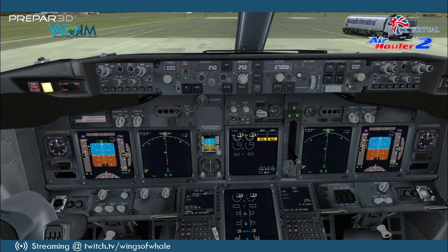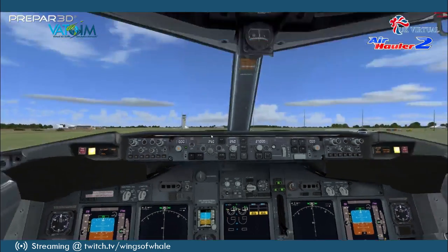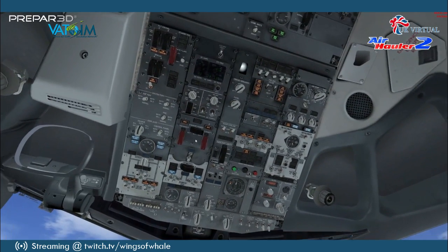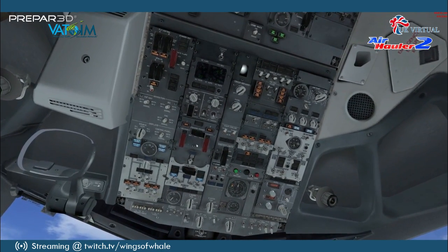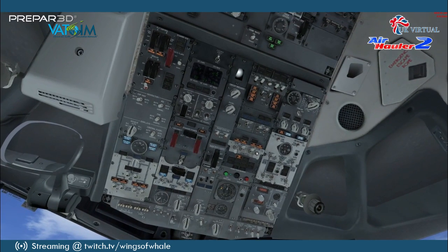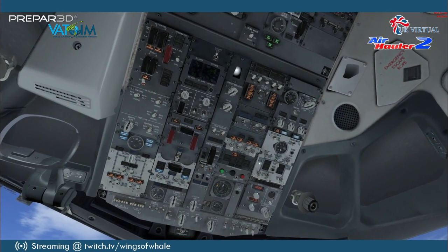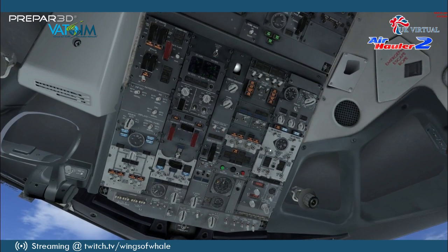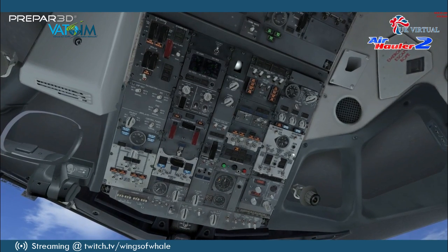Then you would start your flight directors, configure those, and then back up to the overhead panel, and we're ready to start the engine now. Well, both engines now, in fact. So the important things to note for engine start is that your engine packs need to be off.